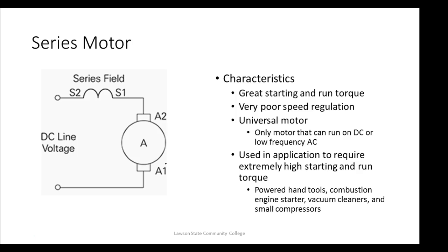You understand? The starter on your car is a what? Is a series motor, right? Tons of starting torque, right? Not really good speed regulation, but a bunch of good starting torque. So anything that needs a lot of starting torque is going to use a series motor. Vacuum cleaners use series motors. A lot of them. Some of them don't, but a lot of them use series motors. Because when you start those things up and you got it down inside your carpet, it's going to require a lot of starting torque.